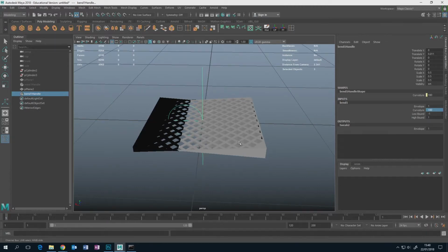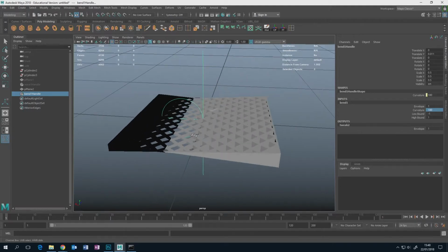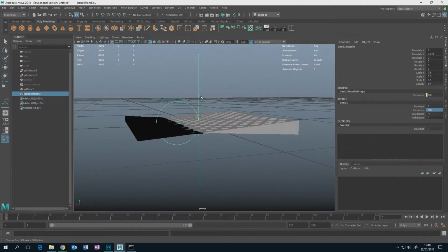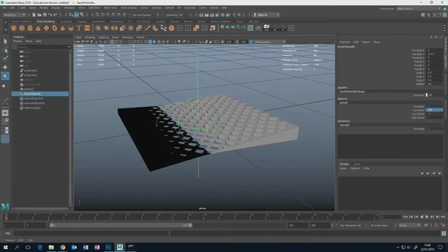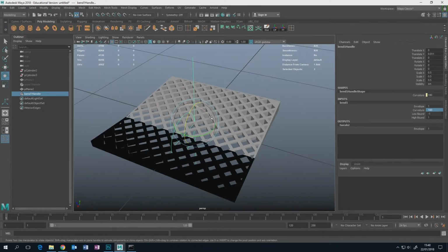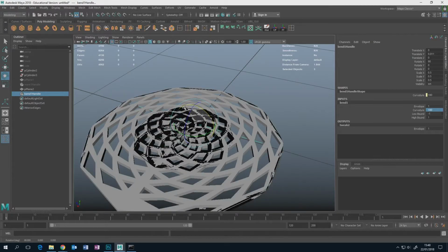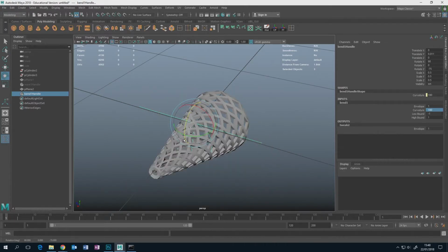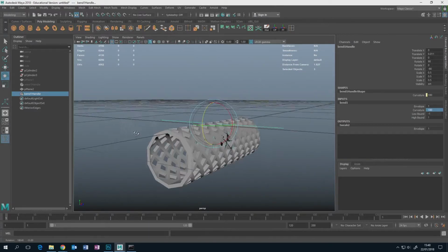So if you apply a nonlinear deformer and it looks a bit strange like that, the chances are that the orientation of this bend handle or twist handle or taper handle or whatever deformer you've chosen is just in the wrong kind of orientation. So you just got to rotate it normally until you find the right rotation. Like that. So I've kind of curved the whole thing in.